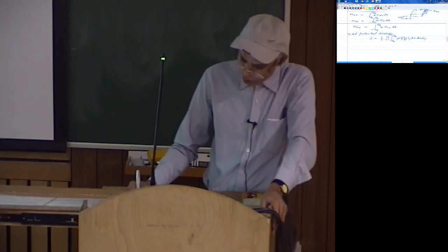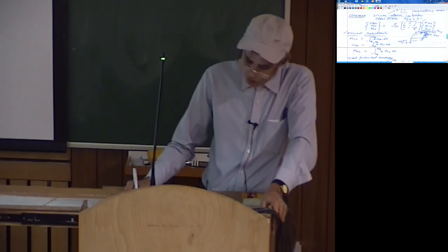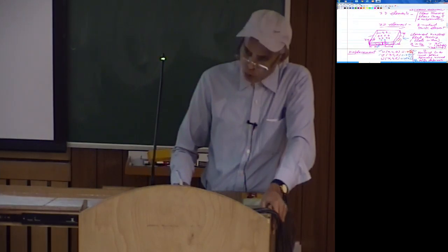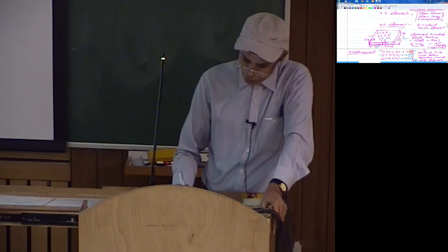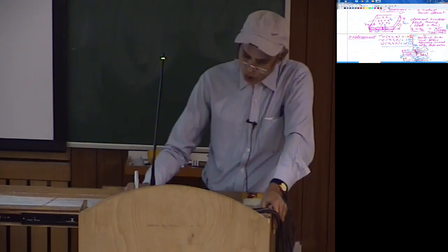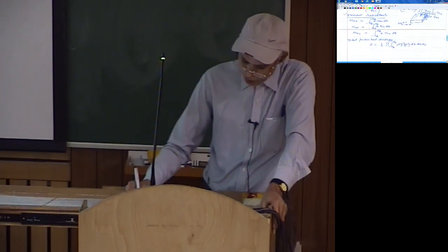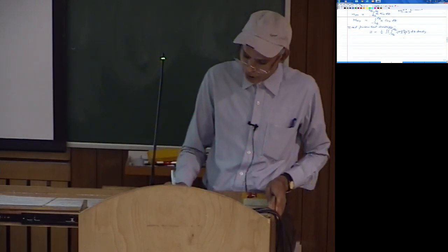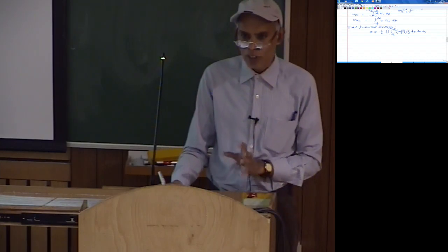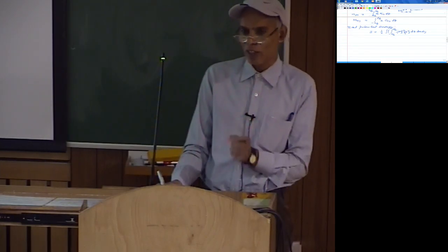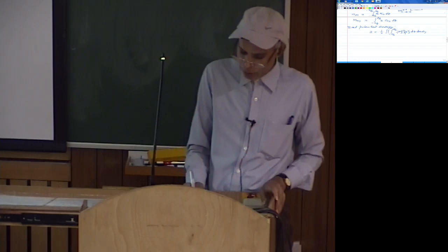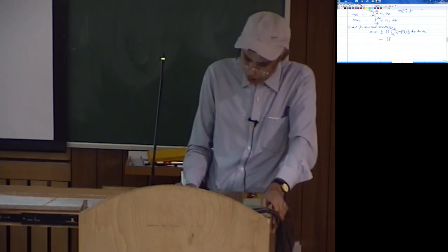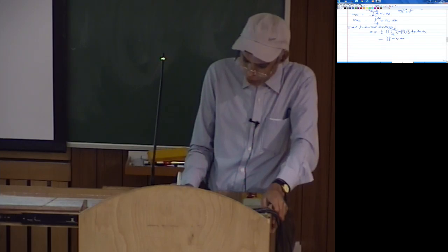Then if you look at external forces and their potential energy, as I said at the beginning, there is a transverse force. Let us say that this force is Q Newton per square meter, that is force per unit area. And that is the force acting along the positive z direction. So Q into dx dy will give you a force over a small area, into W the work done, and minus of that will give you the potential of that. So this would be integration only over area, W into Q into dx dy.